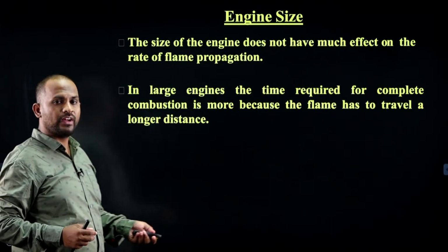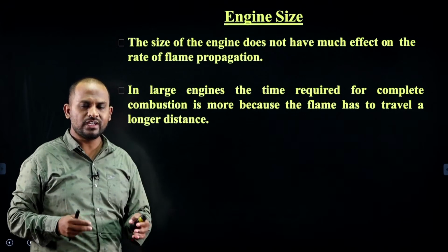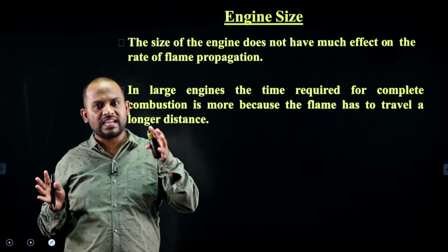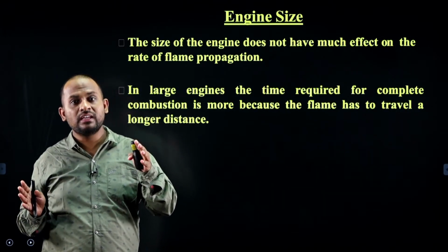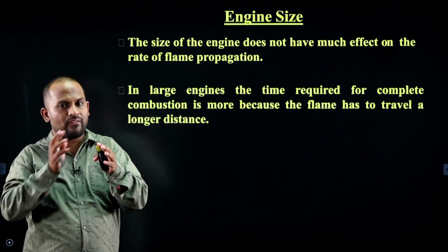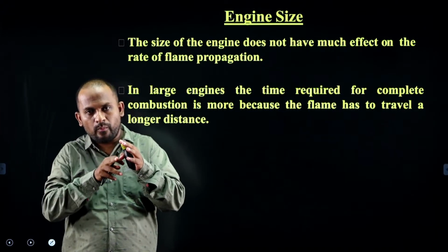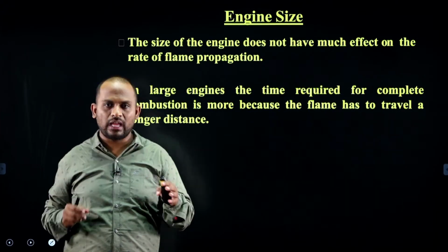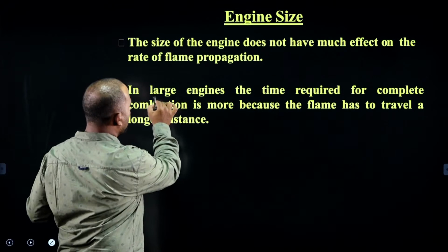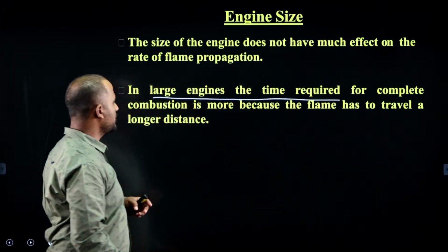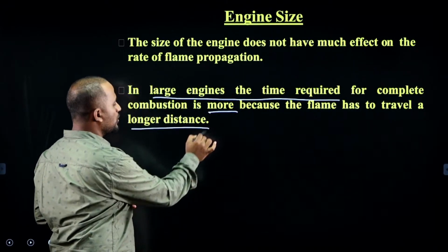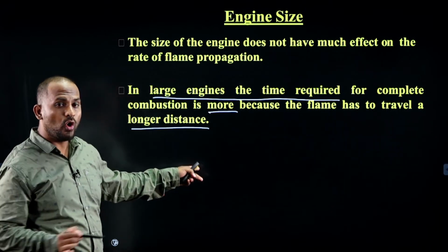Now comes the effect of the engine size. With respect to engine size, there will not be much effect, but when we increase the size of the engine cylinder, what happens during the combustion process? The flame has to travel a long distance. Because of this long distance, the combustion time will be increasing. So in larger engines, the time required for the combustion will be more, because the flame has to travel a longer distance.